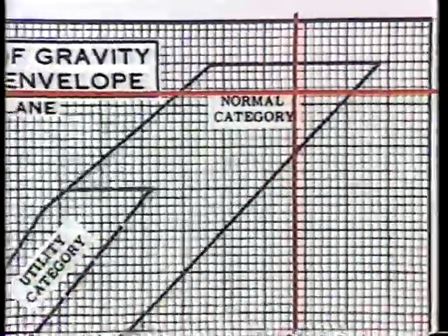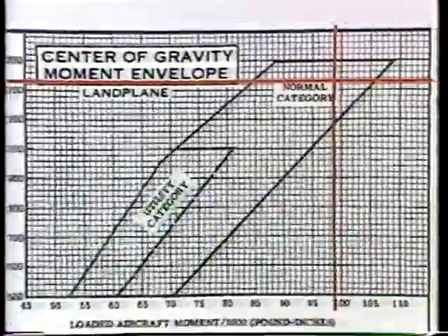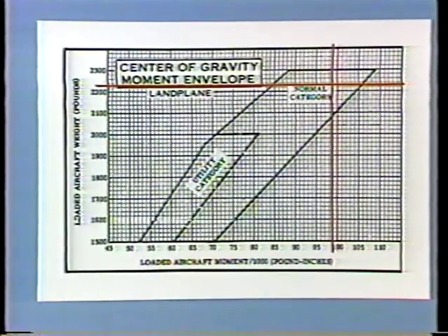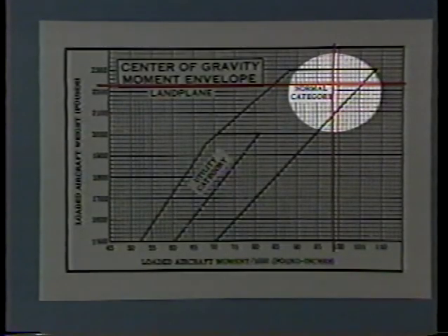If the weight and balance lines intersect right on any of the lines or anywhere within the envelope, then the weight and balance is within the manufacturer's specified limits. The point where they intersect is our center of gravity. Is it inside the envelope? It sure is, and that means we are complying with the manufacturer's certification for both weight and balance.